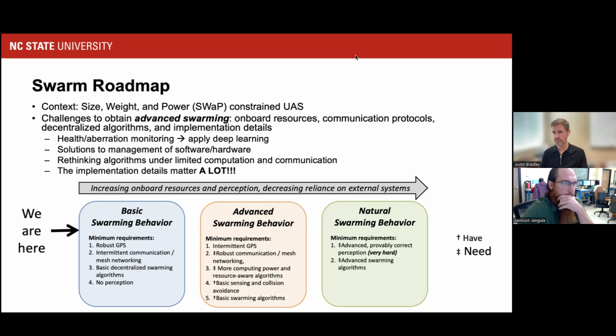Now this changes with a Jetson. The Jetsons are power hungry, and so we often do a separate battery system for a Jetson, and that, as you might imagine, cuts into flight time a lot. But there's not much you can do if you want to run classifiers and neural nets on board a small drone. It's got to be a real thin net, or you've got to have dedicated hardware. They're just not capable of that much.